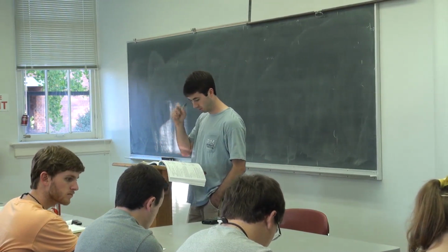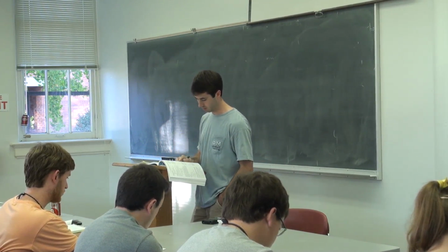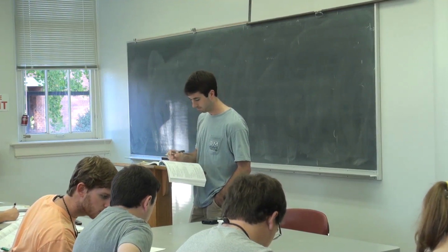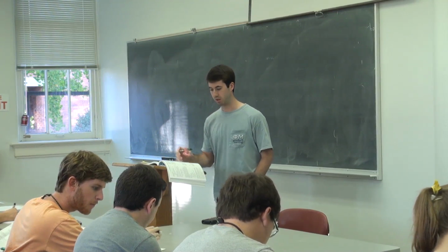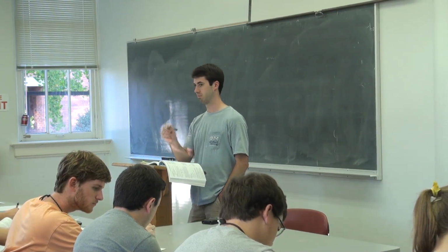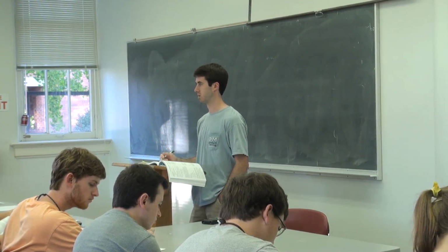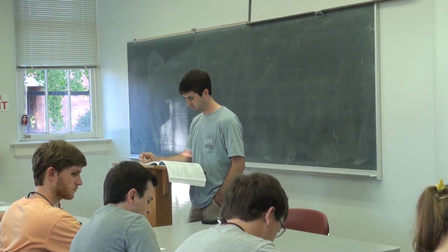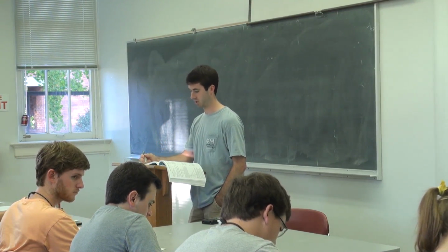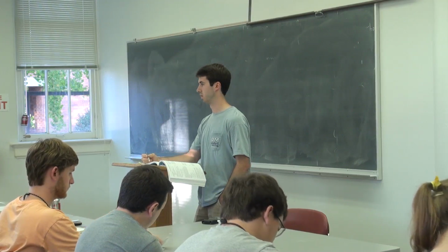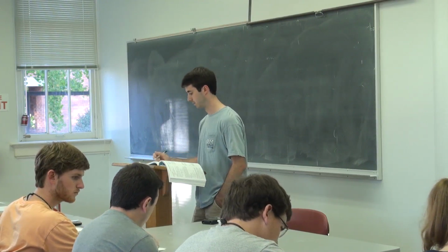So you're given this equation here, K sub I equals something. That K sub I is what you call a stress intensity factor, and it's basically more or less a constant for a given material. In the top right of the page, there's a little table of different materials with these fracture toughness values.